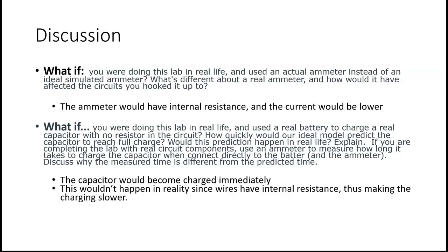What if we were doing this lab in real life and used a real battery to charge a real capacitor with no resistor in the circuit? How would the ideal model predict the capacitor time to fully charge? And would this happen in real life? The capacitor would become charged immediately because there is no resistor. But this would not happen in reality because wires also have internal resistance, thus making the overall charging time and process slower.